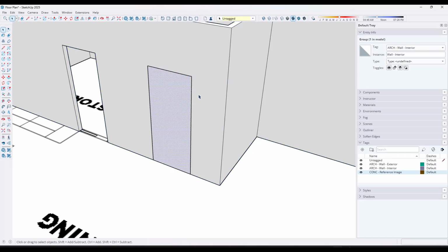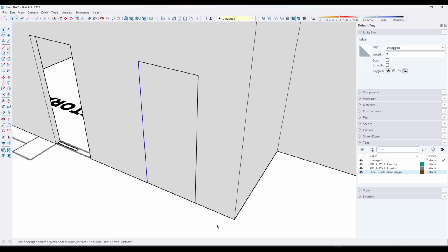And so when I draw a rectangle over the surface, I've now got this rectangle that I can start working with. And I'm going to turn my cursor highlighter on. What I want to do now is select these edges. So I'm just doing a shift click to select all three of these edges. And then I'm going to tap the F key on my keyboard and notice how this little dot pops up.